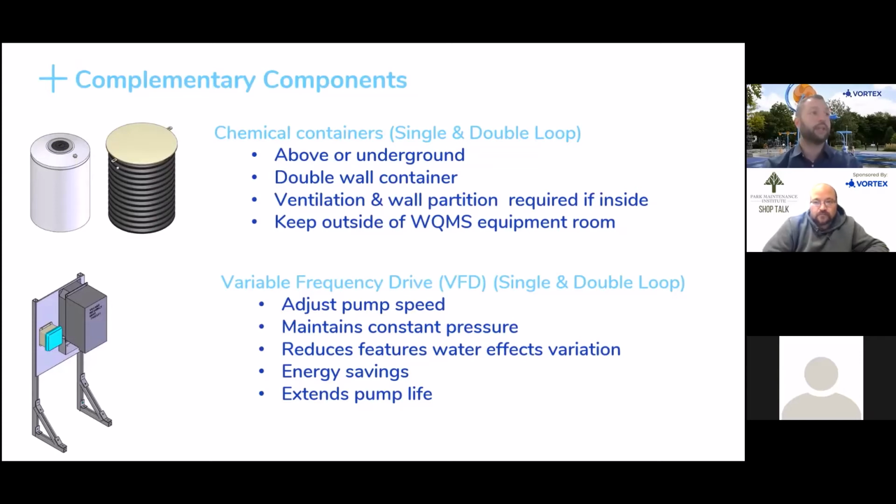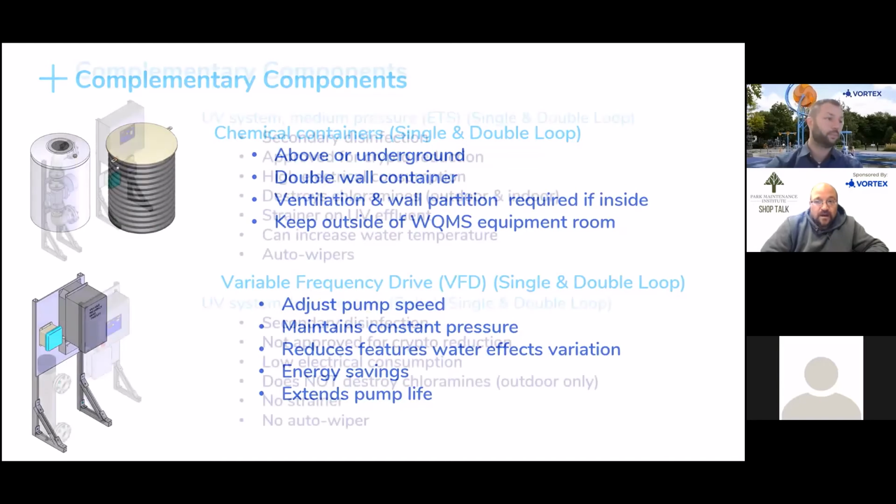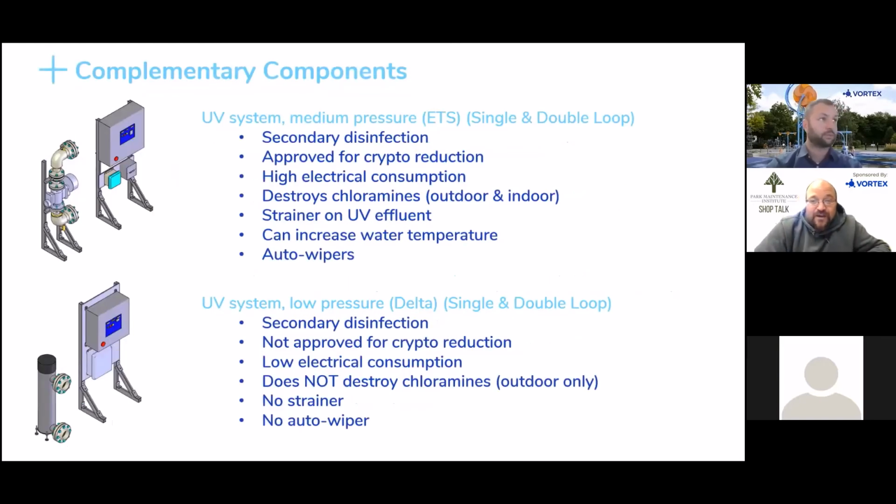Your variable frequency drive, again, we're looking at these having the ability to adjust pump speed, maintain constant pressure, and reduce water feature effect variation. And as far as energy savings and extending pump life, it does really help a lot. I have research to back that up, talking with some other municipalities, specifically in their pools, but the VFDs definitely save a lot of money and they pay for themselves over the life of your equipment. Yep, exactly.